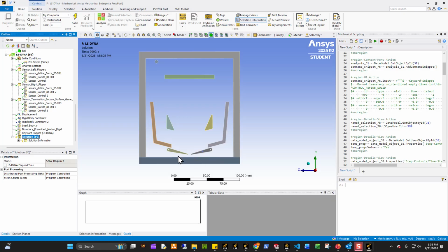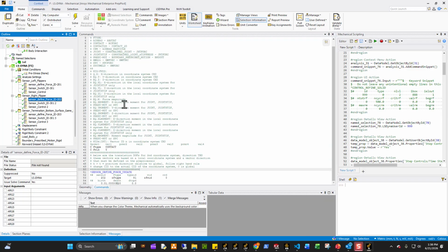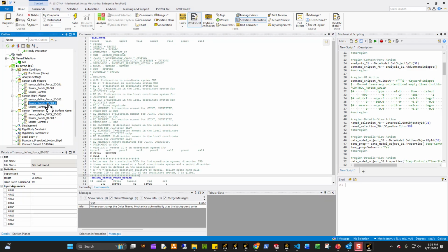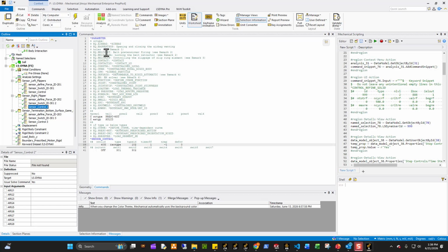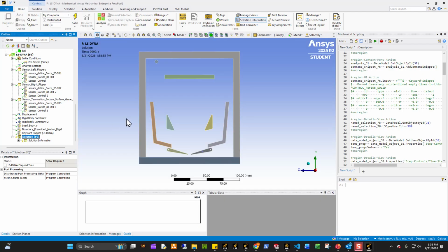And then what we can do is control a lot of different boundary conditions, right? So if you look at the template right here, if you look at control here, you have so many different things you can control, like CNRBs. You can turn on and turn off contact, you can turn off support, you can turn off rigid wall, you can turn off different pressure loads, boundary prescribed motion loads, even different curves, right? So there are a lot of little tricks. You can also do functions. I haven't made an example about functions because it's hard for me to think of one on my own.